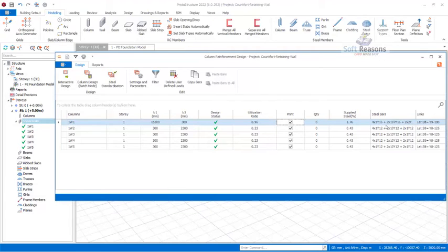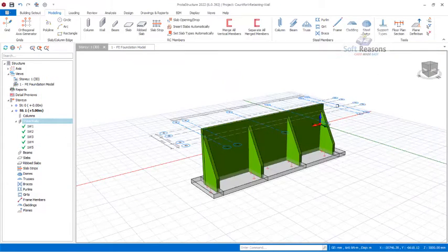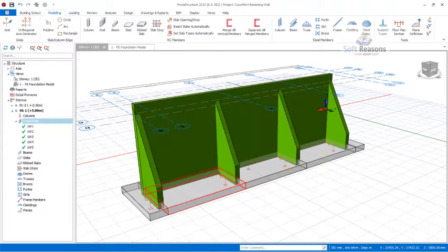the reinforcement generated. So you can see we have all through some Y16, some Y12 diameter of reinforcement, and the spacing of the links varies. As you can see, you have 100 and 125 right there. So these are the information we'll be using to carry out the construction of this counterfort retaining wall successfully. So having done that, we close this. We want to see the reinforcement arrangement.